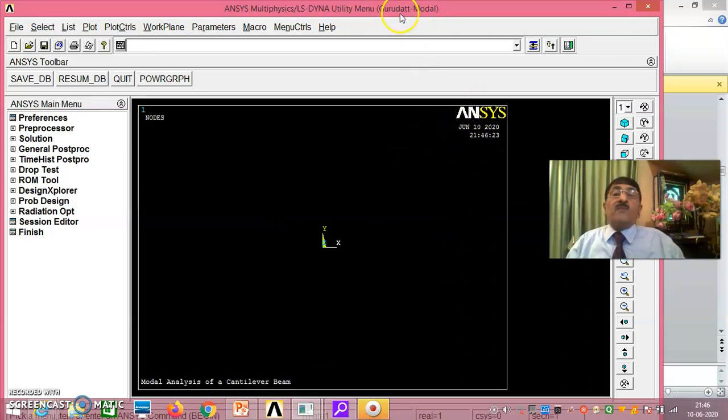And this is a new log file. Whatever we do will be stored here, as I told you in earlier sessions. You can copy this in the log file. Whatever we do using the graphic user interface would have been recorded here. You can copy this and paste it in the Ansys command prompt and get the same answers. You can change the load, everything, whatever changes you want to make, you can do it there and analyze again. I'll tell you in detail in the other chapters.